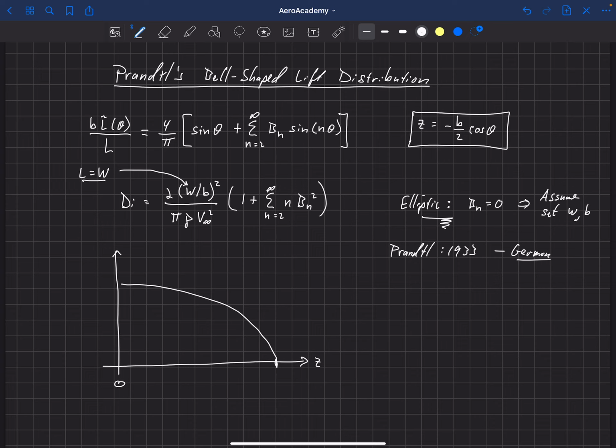Well, the wing spar has to be strong enough to be able to offset that, to be able to withstand the bending moment created by that lift distribution. Okay, so first white here is the lift distribution, and then let's just kind of draw a notional wing bending moment. So the bending moment out of the tip is 0. As you get closer to the root, it increases, and this bending moment depends on what this lift distribution looks like. So we're going to call this bending moment.